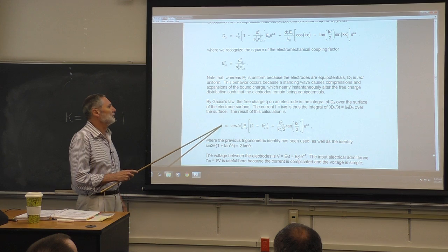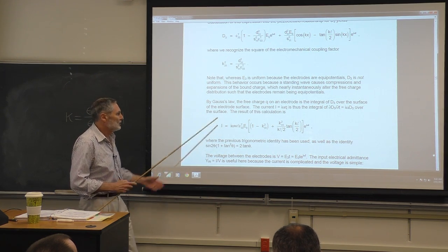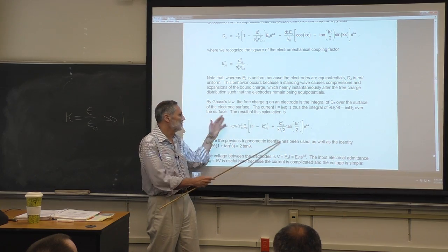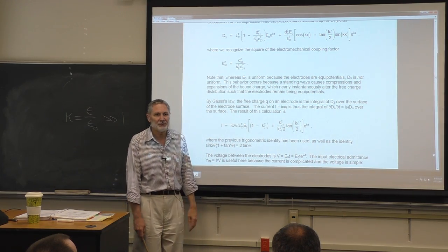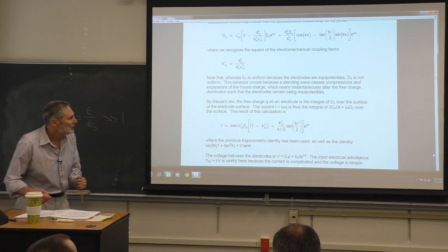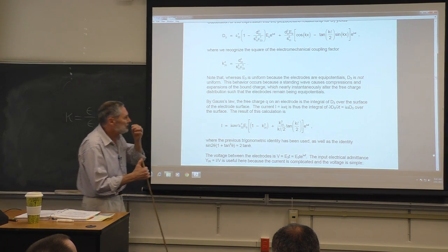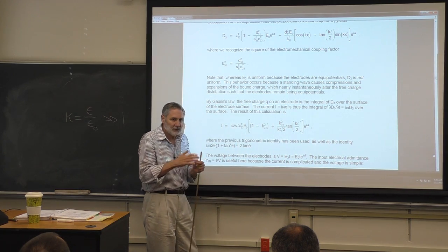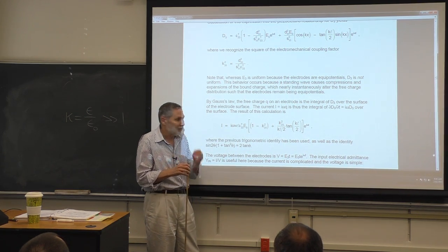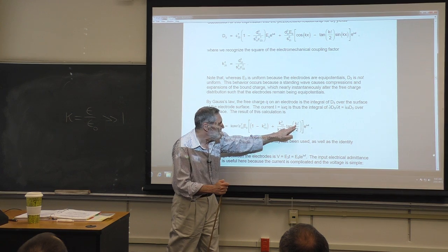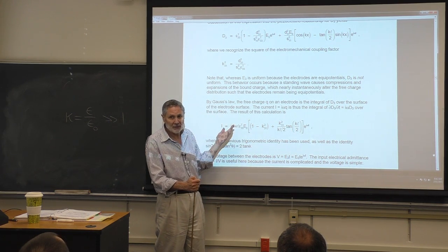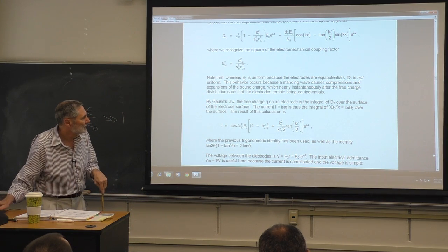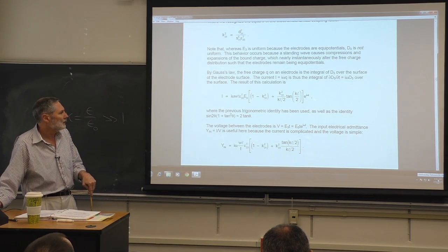So now finally we have the current in terms of the drive. Here's the amplitude of the electric field and all these constants that characterize our piezoelectric transducer. Now you'll notice how we write this. We think of the frequency as an independent variable. Now k, of course, is tied to omega. It's not independent. Omega is equal to ck.